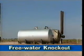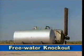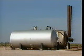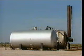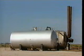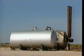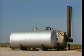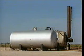A free water knockout removes excessive water from the produced fluid ahead of the treating unit. On some knockouts, a filter or excelsior called hay catches particles of oil entrained in the free water as it passes through the filter. Through gravity, the free water is drained off, leaving only emulsion to pass on into the treating unit. The free water knockouts prevent overloading of the treating vessel and also save fuel.